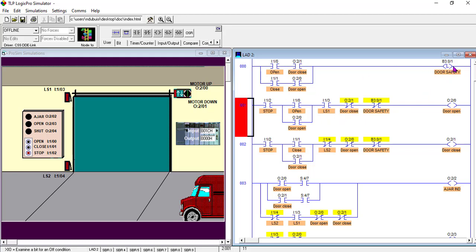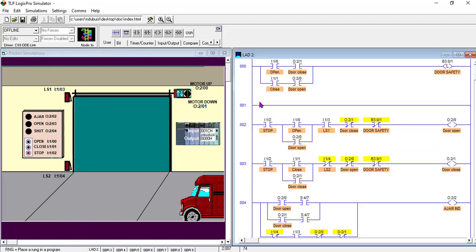After you have been able to stop the door using these 2 contacts, we need to reset so that we can resume operation. It's very important. So add a new rung. We need to reset, so we are using the stop button. The stop button we are using is the second contact of it. Remember that is already a closed contact. So here it has to be in this form. If you close it here again, it will negate the wiring.